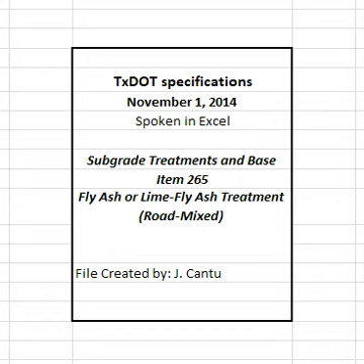4.4 Compaction. Compact immediately after mixing the last stabilizing agent. Use density control unless otherwise shown on the plans. Complete all compaction operations within 6 hours of FA application for Type FS and within 2 hours when using Type CS. Multiple lifts are permitted when shown on the plans or approved by the engineer.